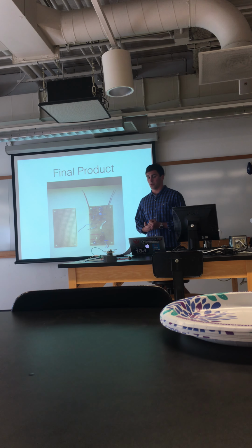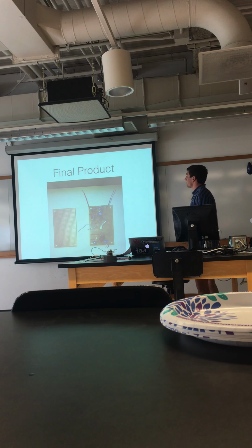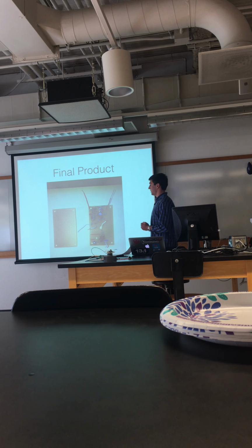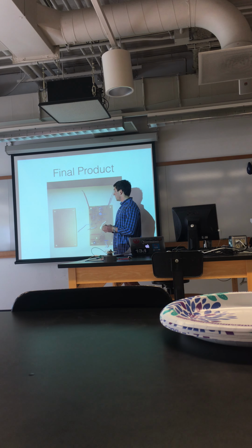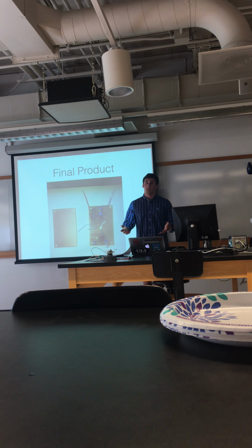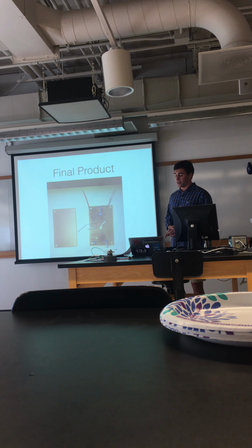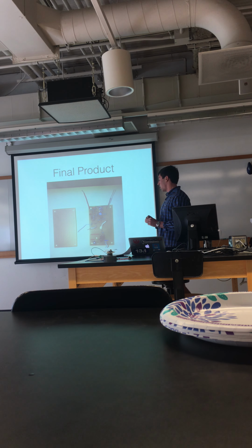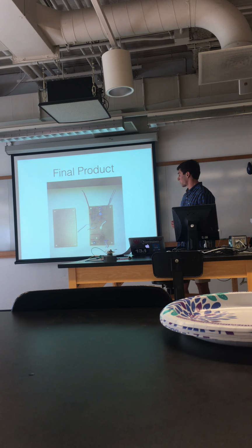And like I said, the board is very small. So the trick is to be really careful and make sure that you don't cross over any solder from one strip to the next, because the strips can't be connected together unless they're supposed to be. But as long as the soldering stays on the individual copper strip that it's supposed to be on, everything is supposed to work fine.